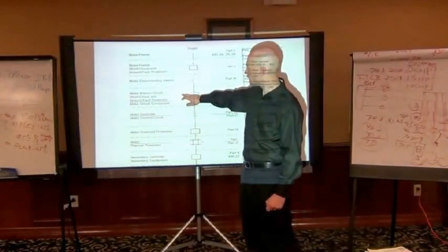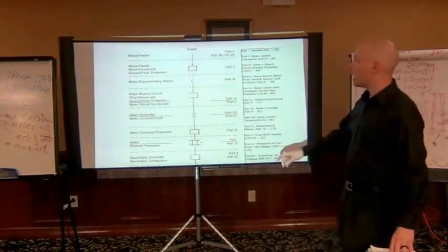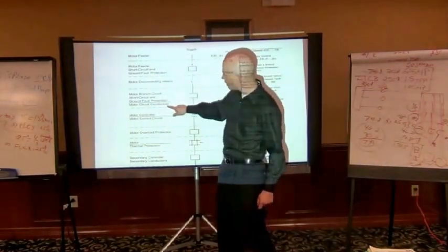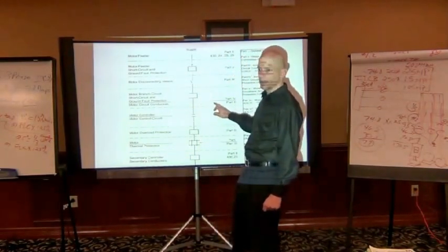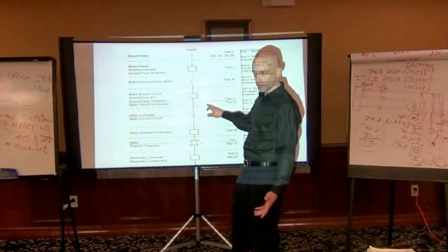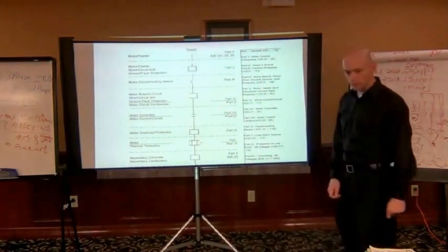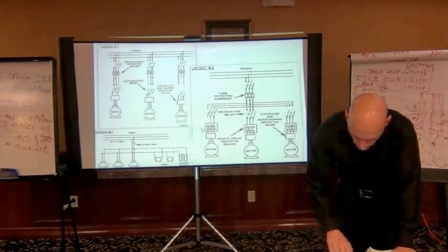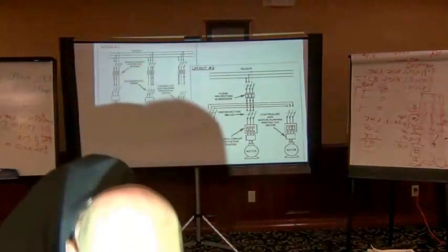22 for conductors and 52 for branch circuit. So his motor feeder would be wired? No, motor circuit conductors right here. Part 2. That's going to be put wire right there, right? And then put dot 22, because that's the article it deals with. Dot 22, remember? That's for a single motor, right? So that'd be 430.22, right? 430.22, that's correct, yeah.